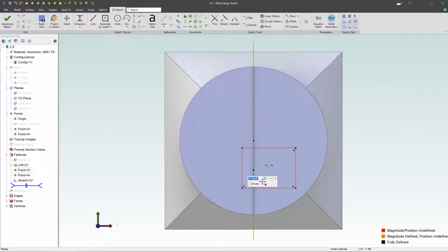And if you want to have it offset, that's great. I mean, you can do that as well. So type in something like an offset, and then just delete it, right? If you delete it, what it does is it activates that point. So then I can grab that center point node, and I can snap it to the other point, and then it's kind of locked together there.